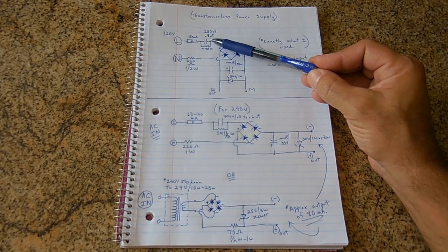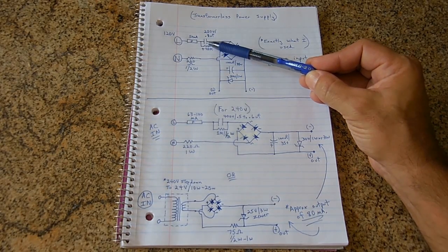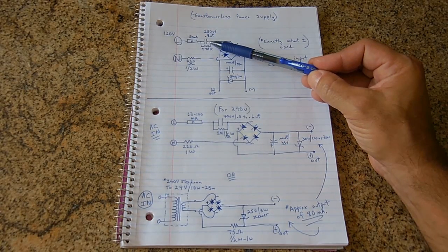If you don't have 0.8 or any other value that you're looking for, remember you can connect capacitors in parallel, and then the capacitance will be the sum of the 2 capacitors. So if you have a 0.47 and you place another 0.47 in parallel, you'll have 0.94 microfarad.